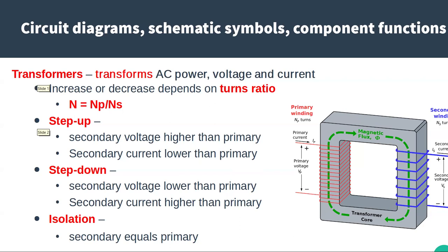That's what you would typically see in a 12-volt power supply or something like a battery charger for a car, where it's plugged into 120 volts, but it's going to put out about 14 volts. So it would have a step down transformer in it, as well as a rectifier.